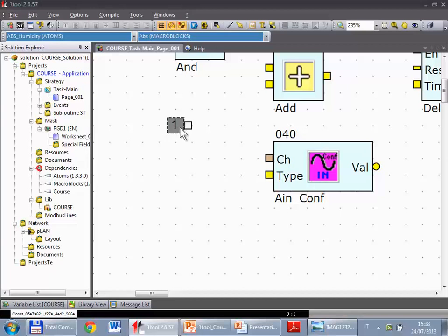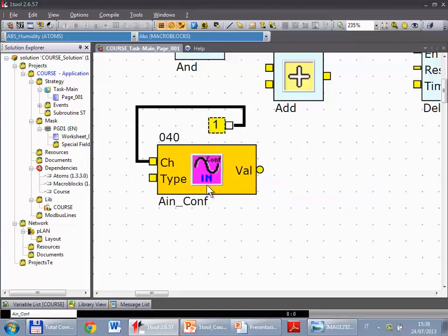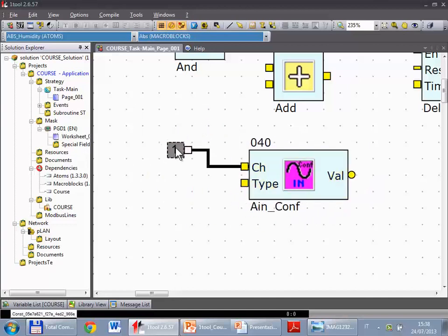Well, now these two objects are not yet connected. To connect them, you have to click one of the two pins from here or here. So click, move, and release. Once connected, they remain connected, even if you move one of them.